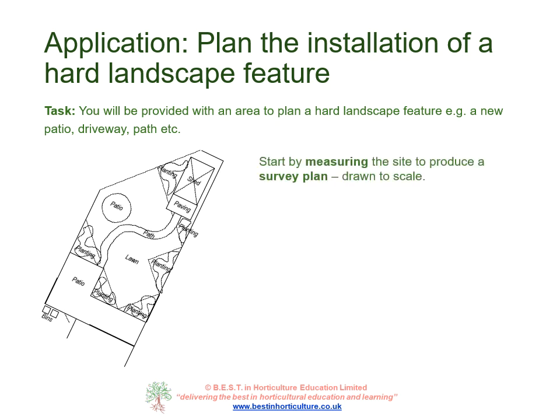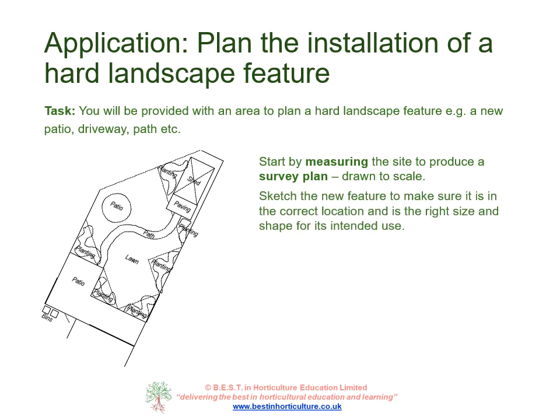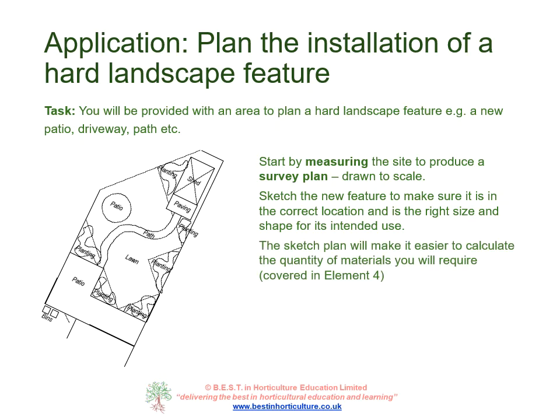In most instances, you'd want to start by measuring the site to produce a survey plan drawn to scale. This will allow you to sketch the new feature to make sure it's in the correct location and is the right size and shape for its intended use. The sketch plan will make it easier to calculate the quantity of materials you'll require, which we'll be covering in the next element.